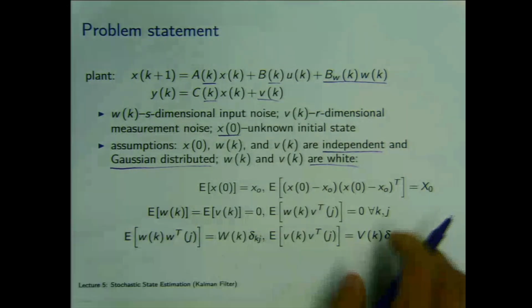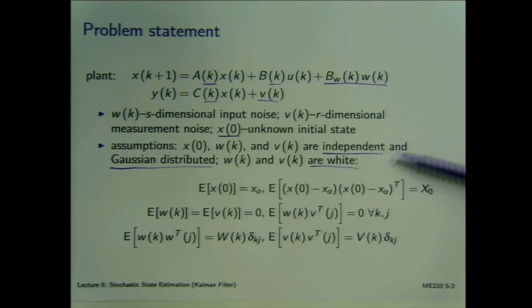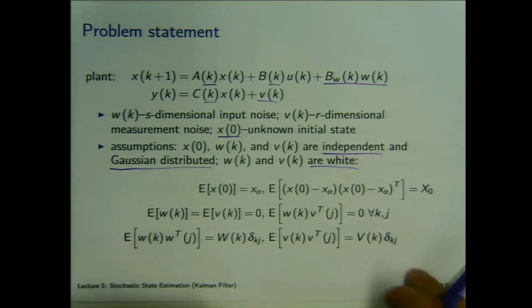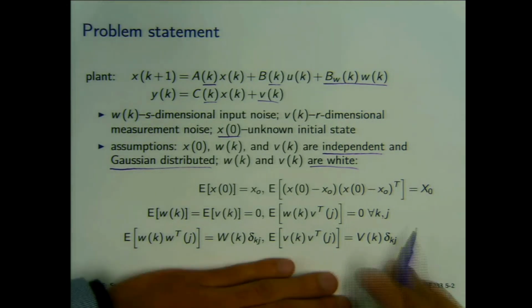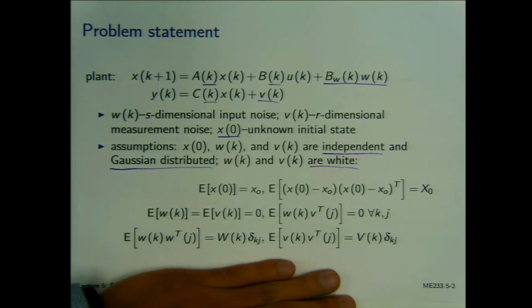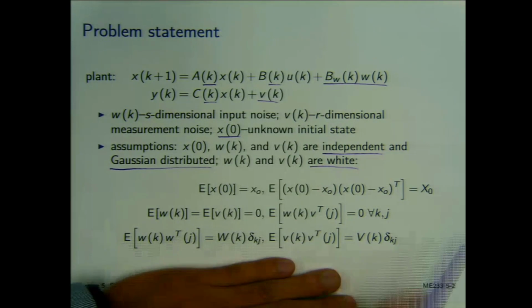So be very careful next time when you are asked to design a Kalman filter. Always check whether these assumptions are satisfied or not. From time to time, you may encounter cases that the problem is not formulated in the exact way as the statement here, and you have to do extra work to make it suitable for applying a Kalman filter. Because actually, Kalman filter itself is not difficult. What's difficult is how you massage the problem into the framework of Kalman filter.